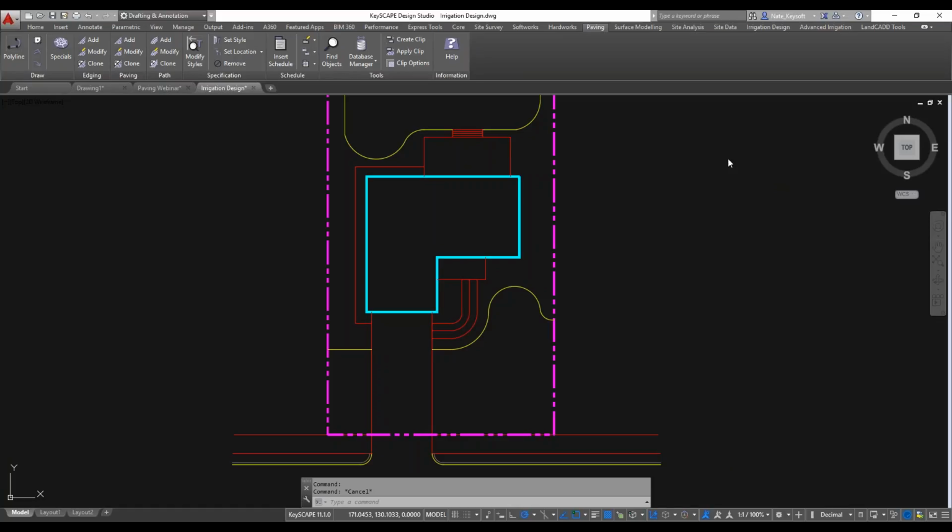This week we're going to be focusing again on the paving module. This is a very useful tool both for doing general quantity takeoffs of paved areas and also laying out complex paving patterns that would normally take manipulation of an AutoCAD hatch or possibly even laying out a pattern brick by brick manually. So today I'm going to go through the basics of this, and then we'll also touch on an introduction of how to create your own patterns as well.